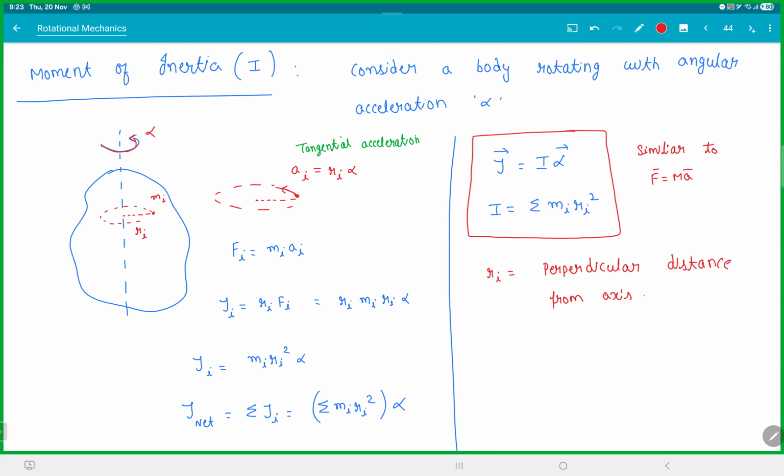The moment of inertia is actually a tensor, right? Again, when I say tensor, let's not get into it, but think of it like this. If I take my phone here, and I catch here and rotate, it feels okay. But when I catch on the edge and rotate, it becomes more difficult. So same body, same mass, same dimensions, but suddenly it became more difficult.